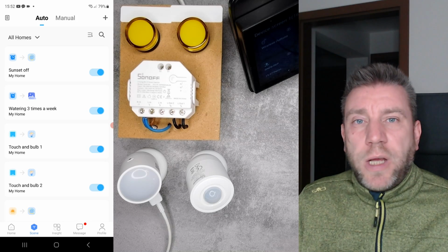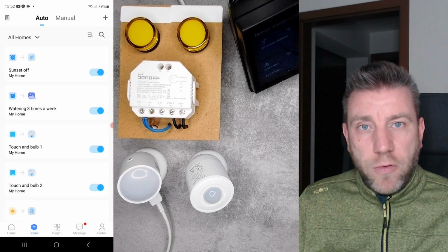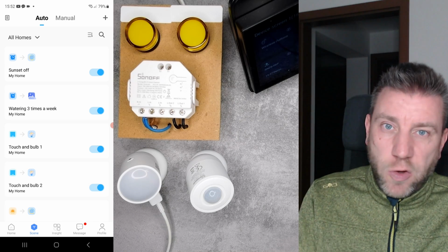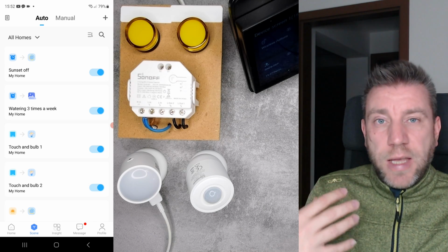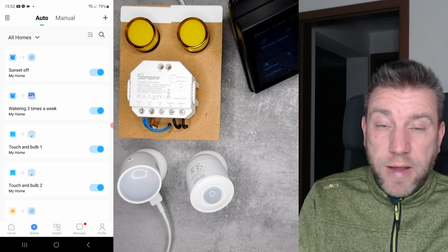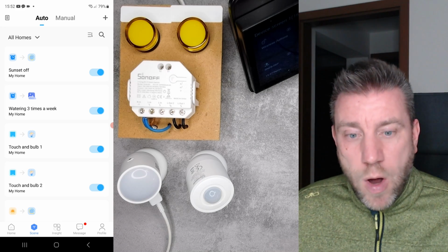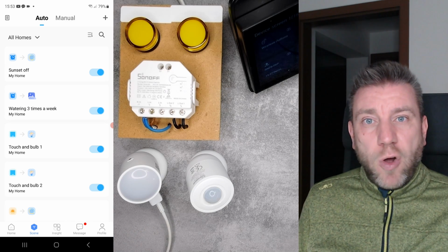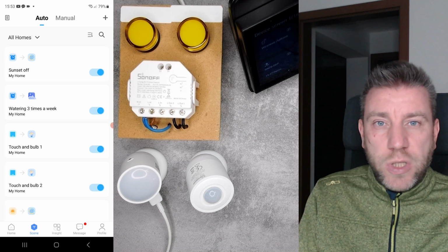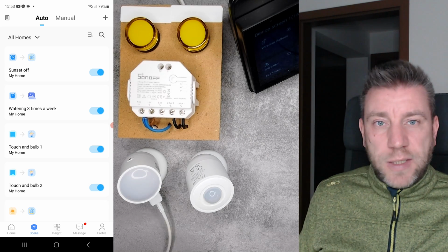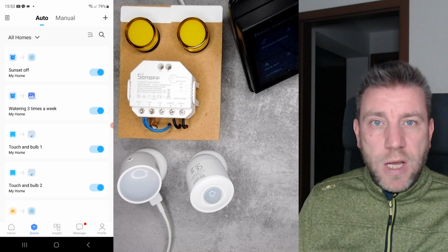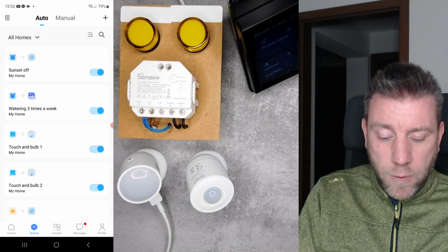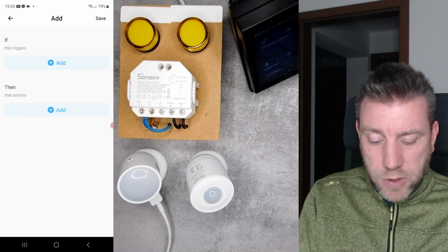And at this point, I want to mention that if you want to use this scenario to light a room where you want to stay for a longer period of time and not just walk in, maybe a toilet or a small utility room or basement, or a staircase, where when you walk in you want the lights to come on, but then you want that room to be lit as long as you are in, then instead of the PIR sensor, you should really be using the presence sensor, because as I said, it is much better at picking up the very small amount of motion when you are just sitting, or if the sensor is really close to you, like 1 or 2 meters, it basically picks up your breathing and senses that as a presence.